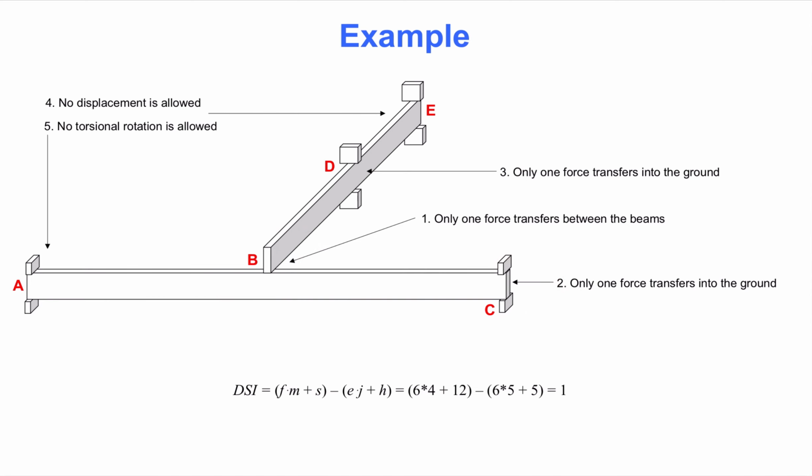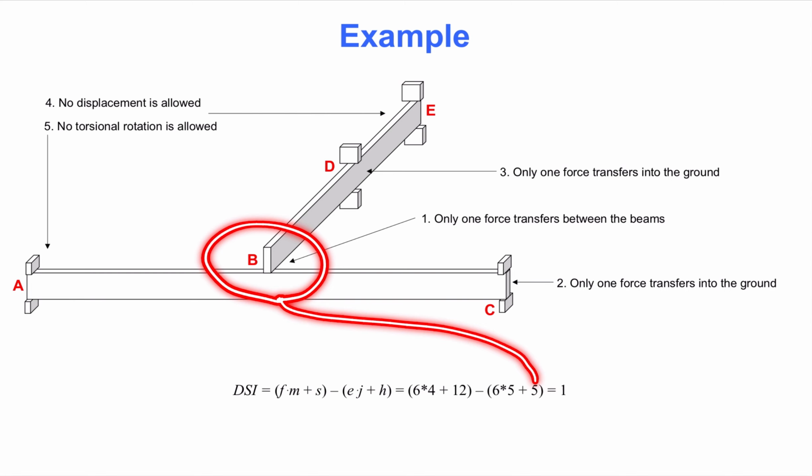However, there are different ways of doing this. For example, an equivalent approach, in terms of making the structure stable, is to prevent rotation about the weak axis of each beam, namely about the vertical axis, at point A and point E. As a result of all these assumptions, we have a total of 12 support reactions. That includes 5 at point A, 5 at point E, 1 at point D, and 1 at point C. We also have released 5 of the 6 internal forces in the beams at point B.